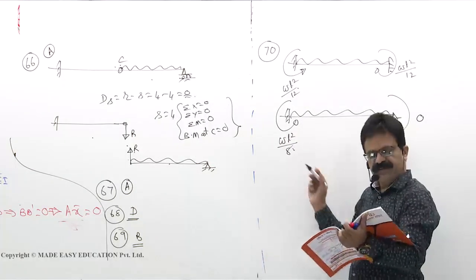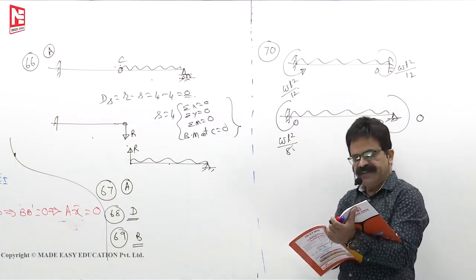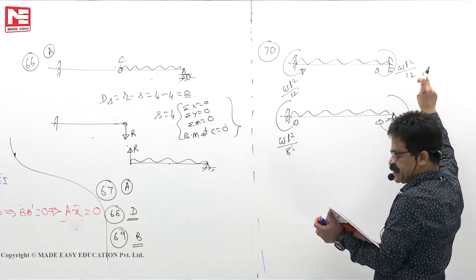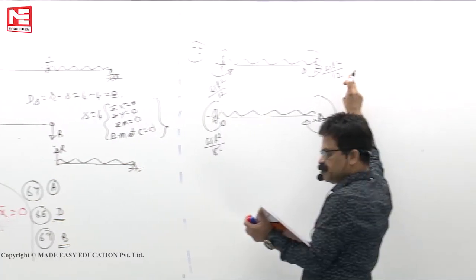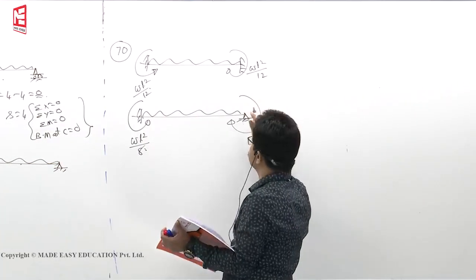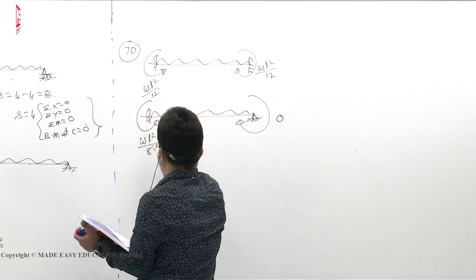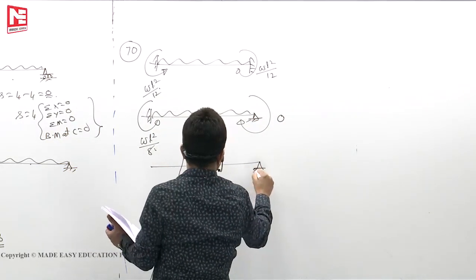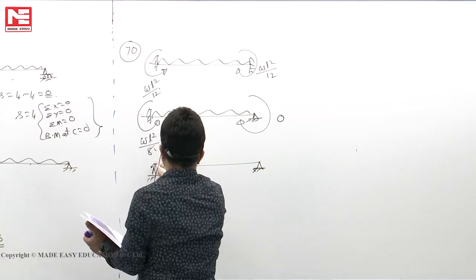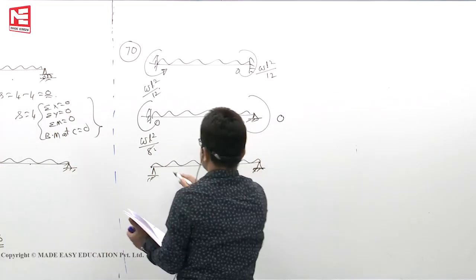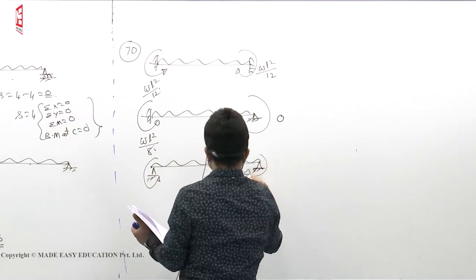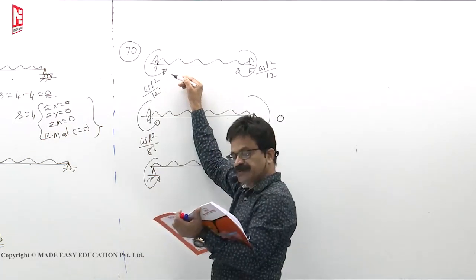We solved. Now let us see what is the question. If degree of fixity at supports is lessened, maximum hogging moment at the ends will decrease. That means this is also a hinge. Both ends will now be taken as hinges. Degree of fixity is lessened, so hogging moments now will become 0. Here hogging moment is more.